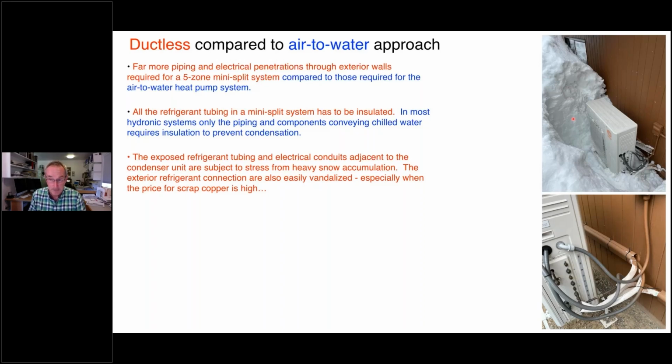It wasn't operating under that condition, but imagine the weight that would be on this tubing down here. And if you look carefully here, you can see the weight that was on it has pulled that refrigerant tubing out of that plastic enclosure. It actually broke open the plastic enclosure. Here's kind of a zoomed in view. Somebody had repaired that with zip ties.